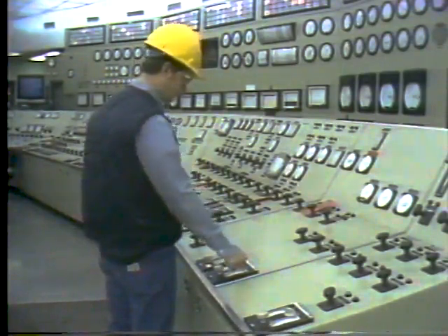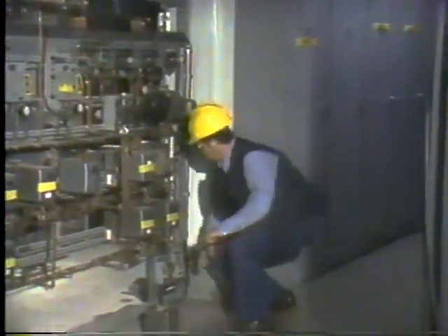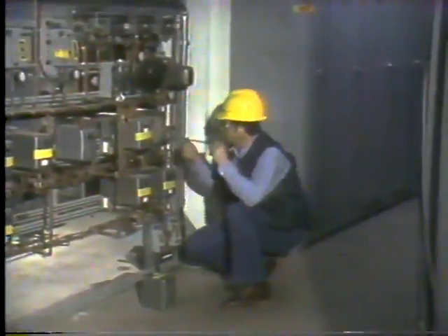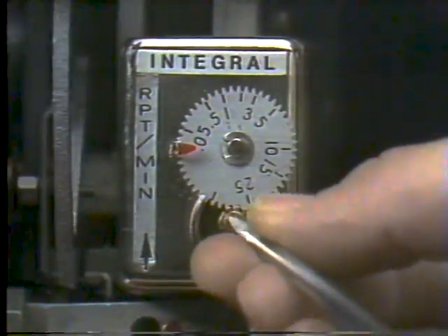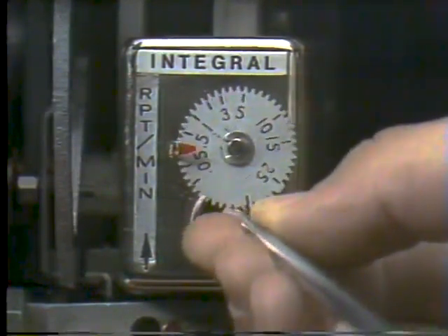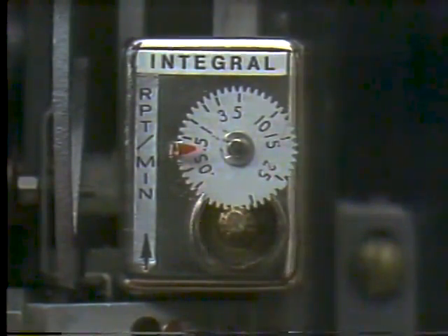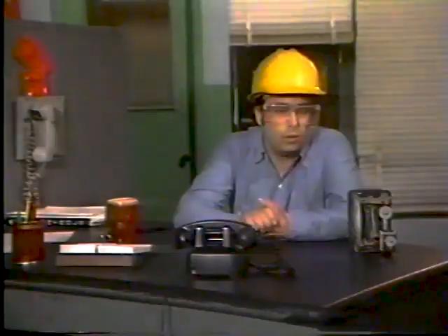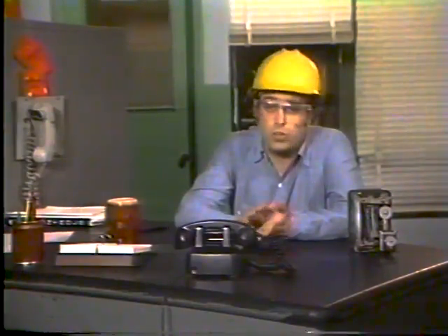He began by switching the system to manual and went to the controller to adjust reset to 0.2 repeats per minute. 0.2, as you recall, is the setting that was suggested by the engineer and was considerably lower than the old setting of 1 repeat per minute. The engineer's suggested setting was pretty low because the new gain setting was expected to be about twice as high as the old one. Higher gain results in less offset, so the system shouldn't have needed as much reset action.